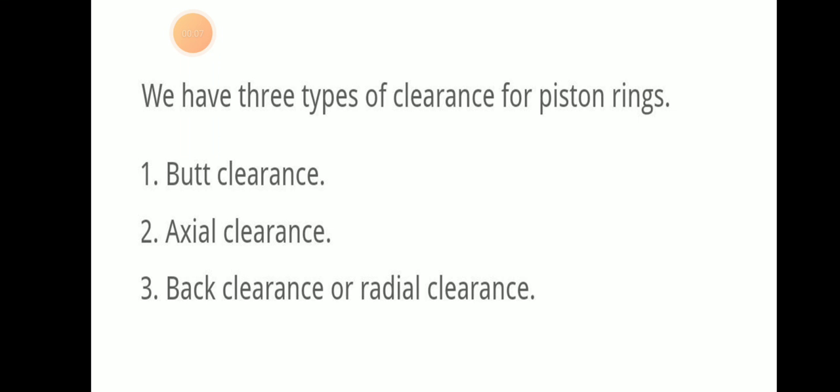Today we will be discussing piston ring clearance and its different types. There are three types of piston ring clearance: butt clearance, axial clearance, and back clearance. Back clearance can also be called radial clearance.